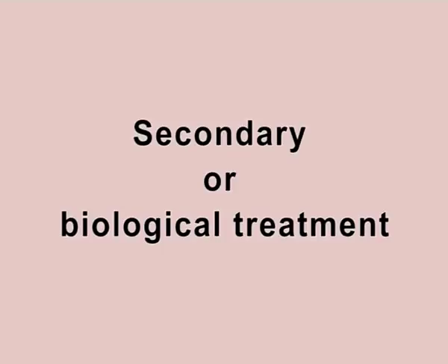The secondary treatment, which is generally called the biological treatment process, includes aerobic and anaerobic degradation of the waste in the liquid. In several countries, most of the food processing plants deliver the wastewater to municipal systems after primary treatment. But in some cases, the wastewaters may pass through a secondary biological, which includes aerobic and anaerobic treatment process.